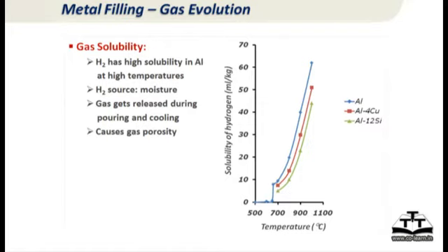But the absorbability of that same gas, once the temperature falls to room temperature, let us say 20 or 27 degrees after solidification, is hardly 10 milliliters, which means something like 6 to 7 times the volume of gas has to come out. And 50 milliliters of gas per kg is not a small amount. Finally, it all becomes gas porosity and goes into the metal.